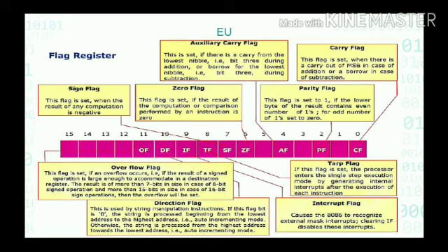Then overflow flag. This flag is set if an overflow occurs, that is, if the result of a signed operation is too large to be accommodated in the destination register. If the result is of more than 7 bits in size in case of 8-bit signed operations, or more than 15 bits in case of 16-bit signed operations, then the overflow flag will be set. Status flags are updated after every arithmetic and logic operation.